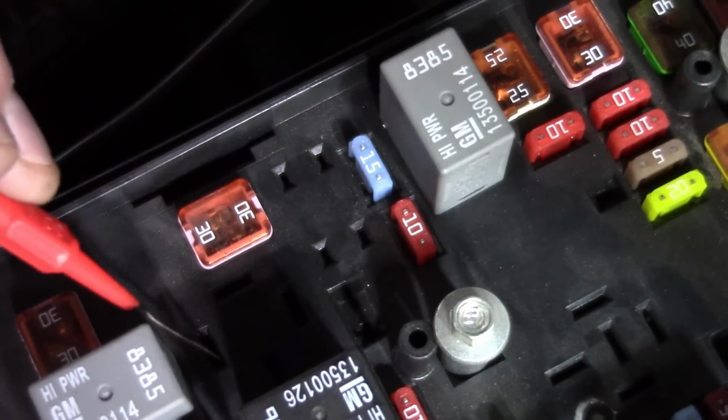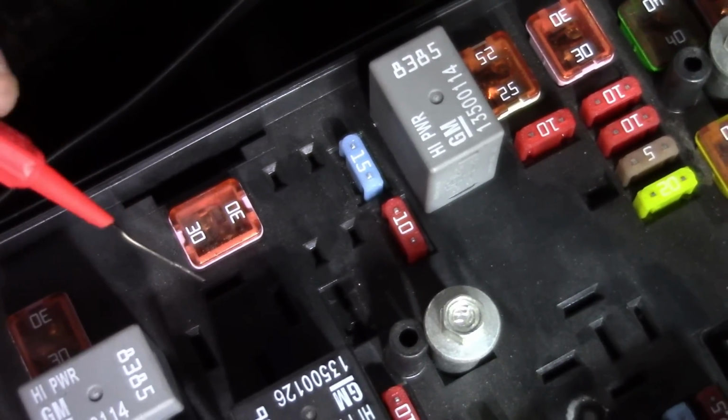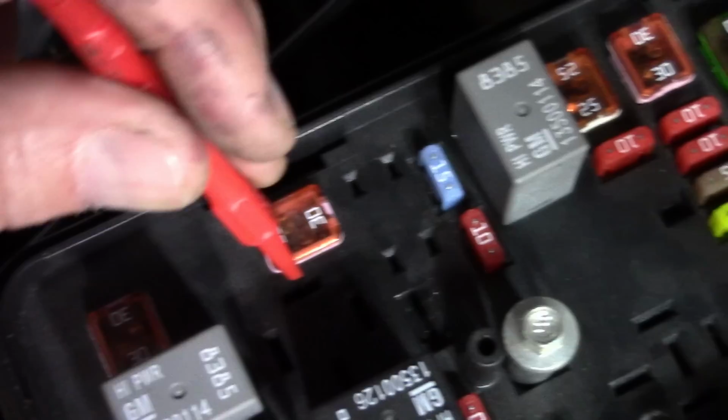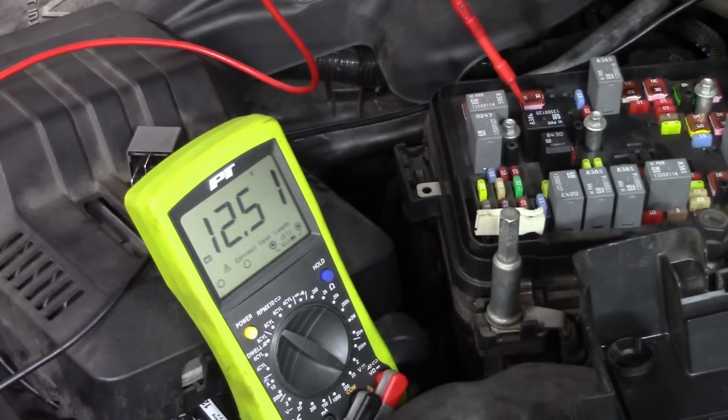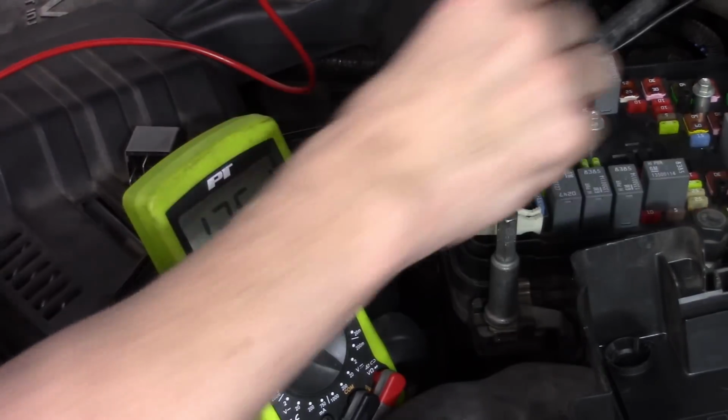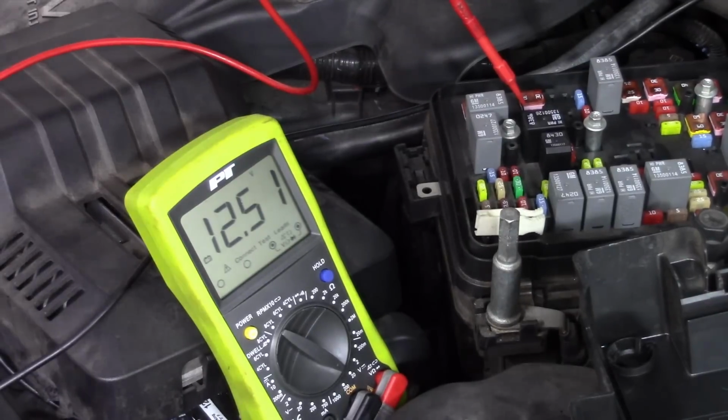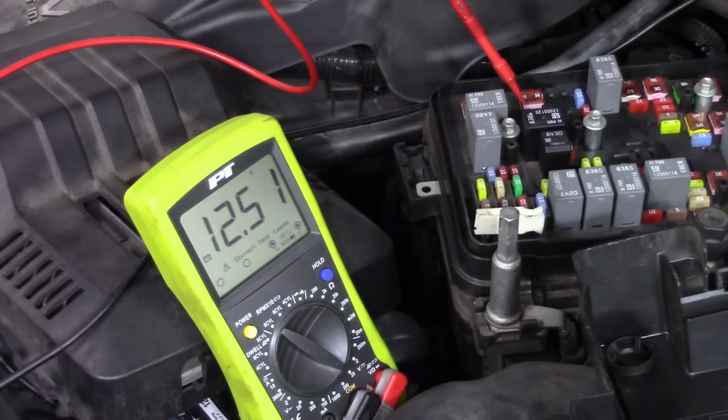85 and 86, the control side will be these ports. So I'm just going to stick my probe in here, and that is a power. If we see we found power at all times on this port, we don't even have key on here. This means we can be very specific now on identifying the terminals of our relay.